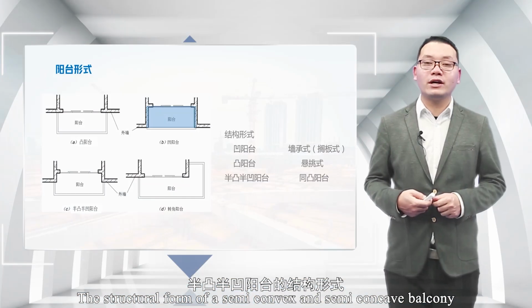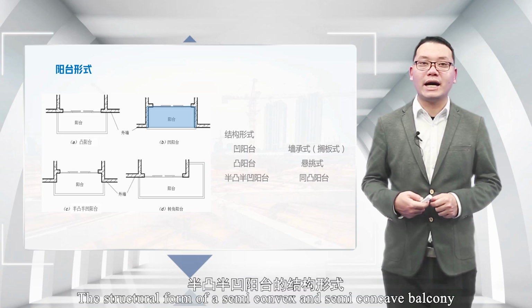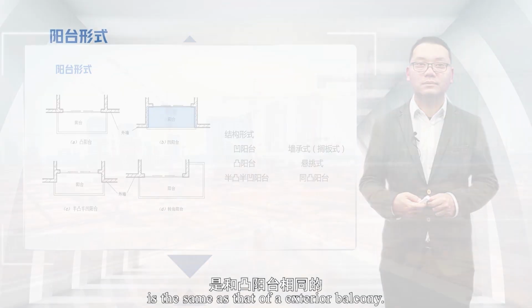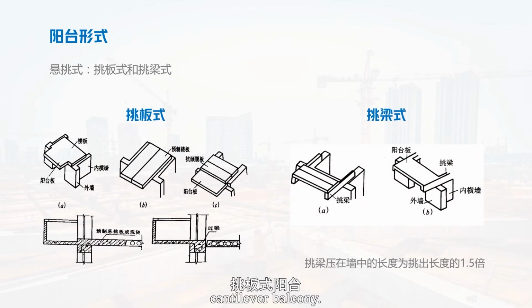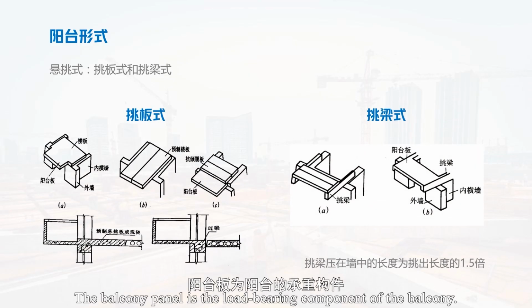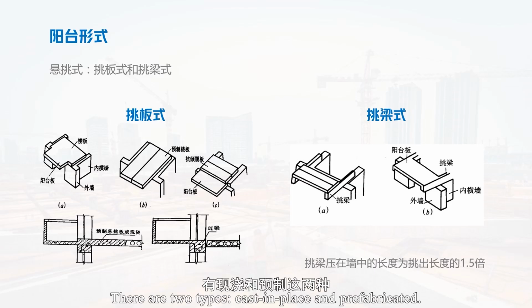The structural form of a semi-convex and semi-concave balcony is the same as that of an exterior balcony. Cantilever balcony: the balcony panel is the load-bearing component of the balcony. There are two types, cast-in-place and prefabricated.